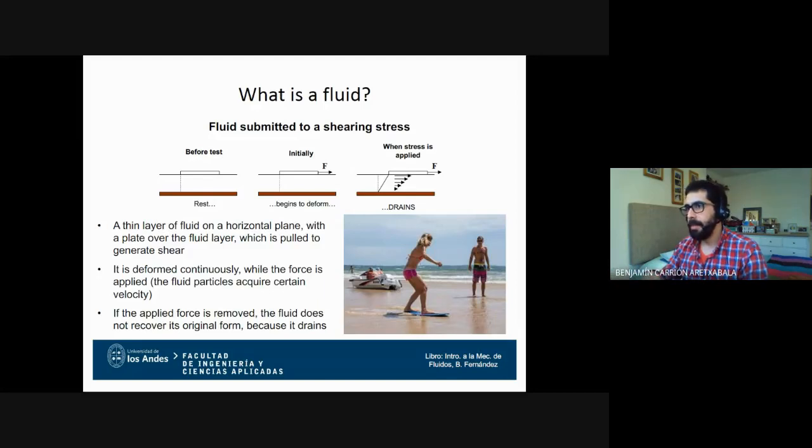Say you have a table and you put a very heavy object on it, or you sit on the table. You're putting a pressure on the table. It is a stress, because pressure is a stress by definition. But a shear stress would be if you're sitting on the table and a lot of people grab you and start dragging you on top of the table.